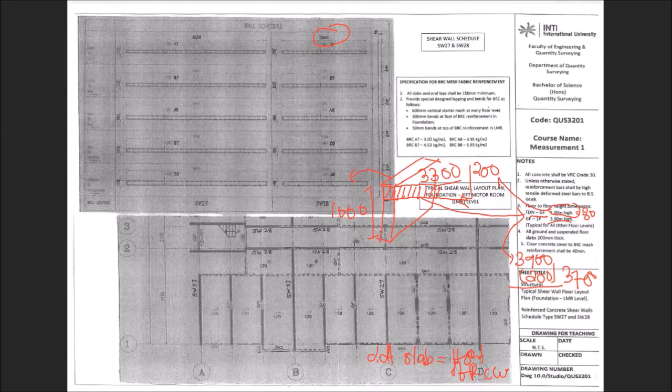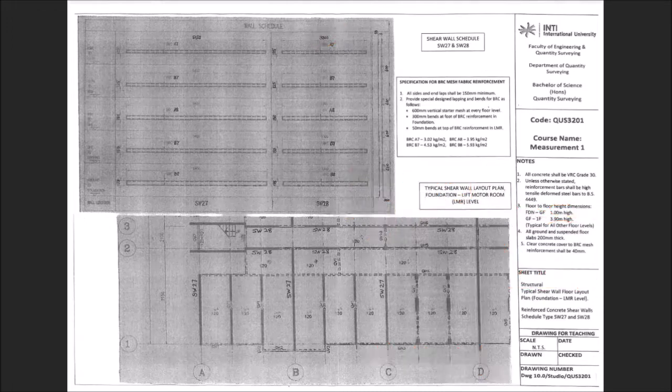Okay, height also will influence the way you measure for BRC and the way you measure for formwork. Remember, the height that is more than 3.5, you have to state and measure separately. There are specific clauses mentioned about that. Okay, so this information is very important for you to take note.